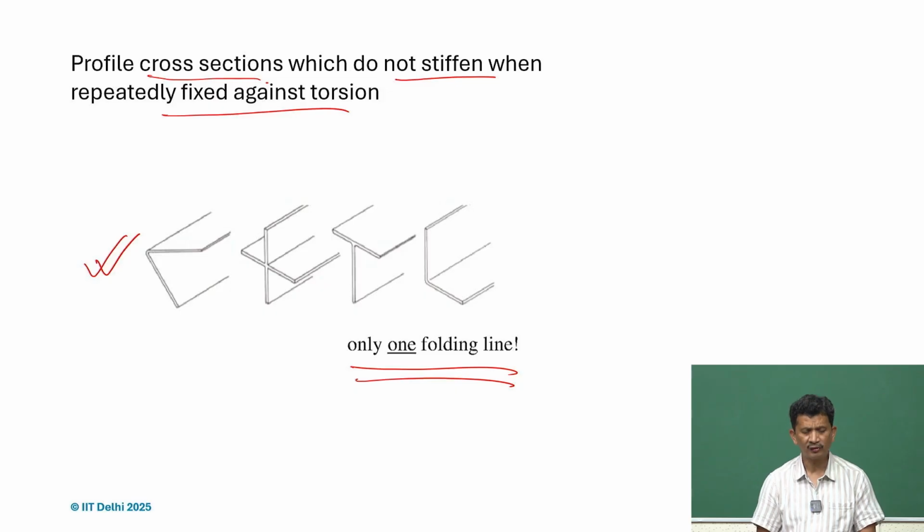And the obvious reason is under the torsional load, there is no warpage. So many times it stays in the inner plane, and that's the region. It's very difficult to stiffen them just by closing the end. So these are compliant members, torsionally compliant, and unlike in the other case, if we have these kind of sections, it's difficult.